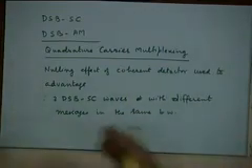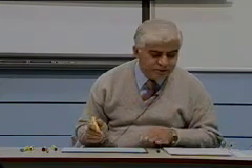The spectral occupancy of both the modulated signals would be in the same fc plus or minus B hertz, right? So if you can do that, what would you do? You would increase your bandwidth efficiency by a factor of 2. In the same bandwidth where you were transmitting only one message, now you are transmitting two messages.